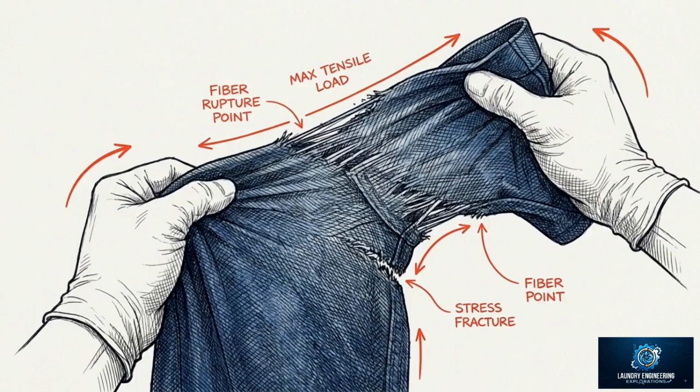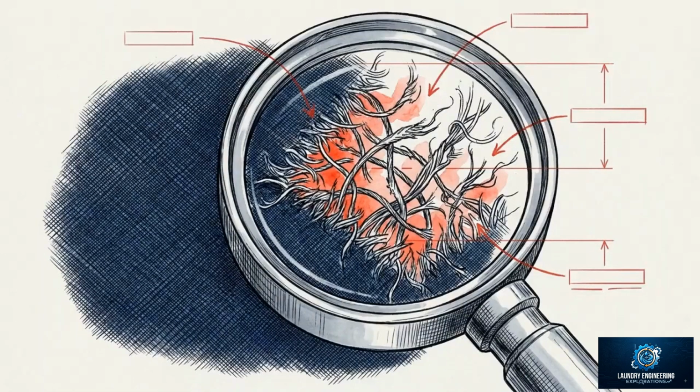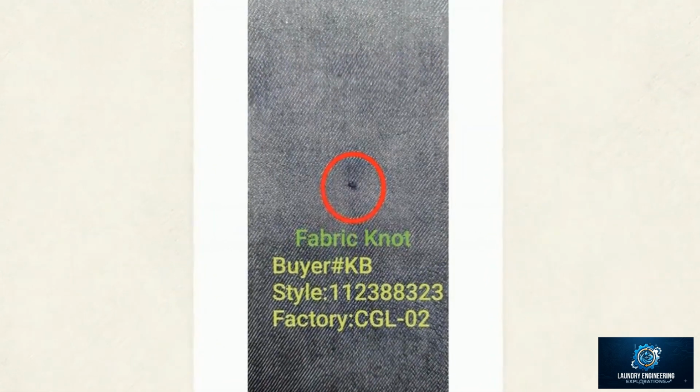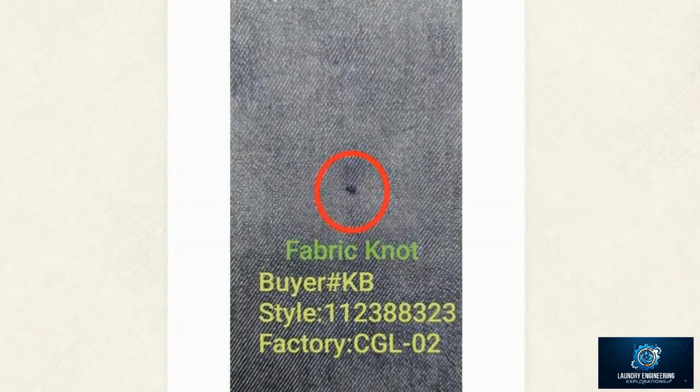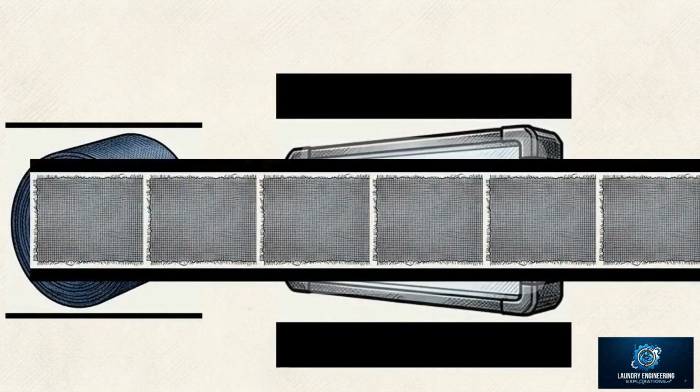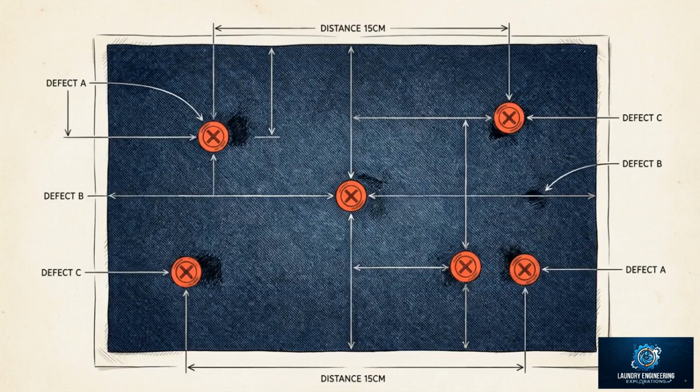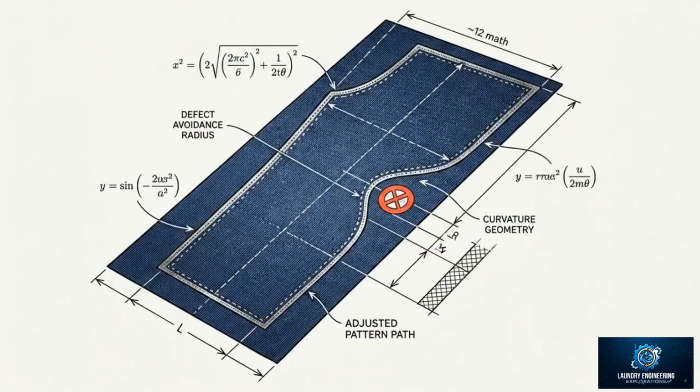They point directly to upstream raw material inspection failures and extreme instances of mishandling. Here is the visual evidence of upstream fabric faults. Notice the irregular yarn slubs, weft breaks, and this prominent raised yarn knot embedded right on the face of the denim weave. The root cause is a failure at the warehouse level to conduct an adequate 4-point raw material inspection prior to the spreading and cutting phase. As an immediate corrective action, quality control must actively flag these fabric flaws with bright stickering during spreading. This ensures pattern cutters know exactly where to avoid defective zones.